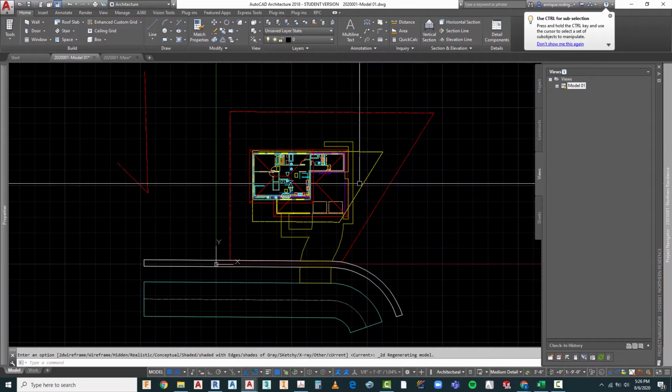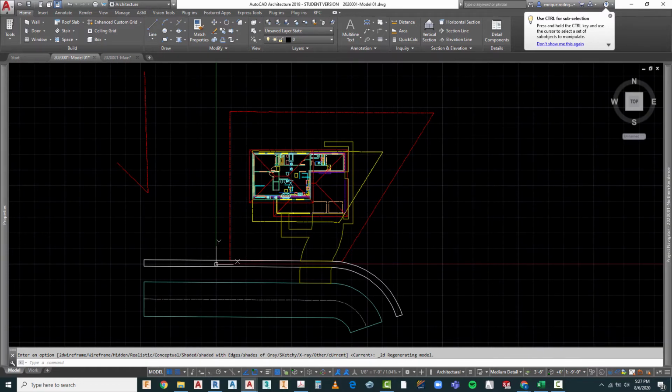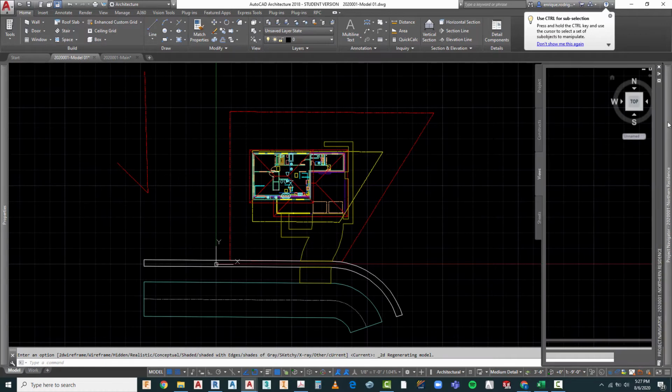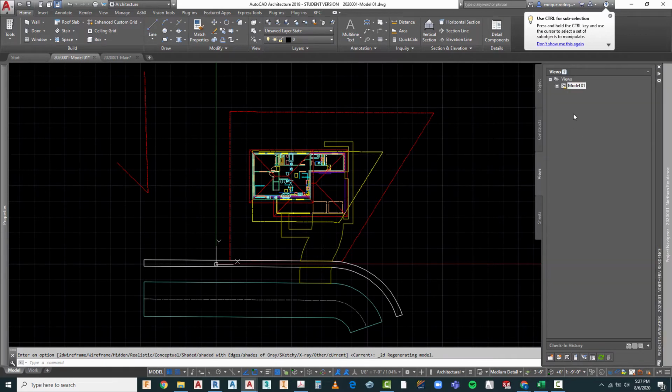So the first thing that we want to do is form a view drawing, a DWG, under our Views tab, that contains all 3 elements. Almost identical to the model, but we're going to create a separate view for our elevations. We could technically use the same view assembly or composite that we have in here, but for the sake of identifying it as a separate item, we're going to create another view drawing.